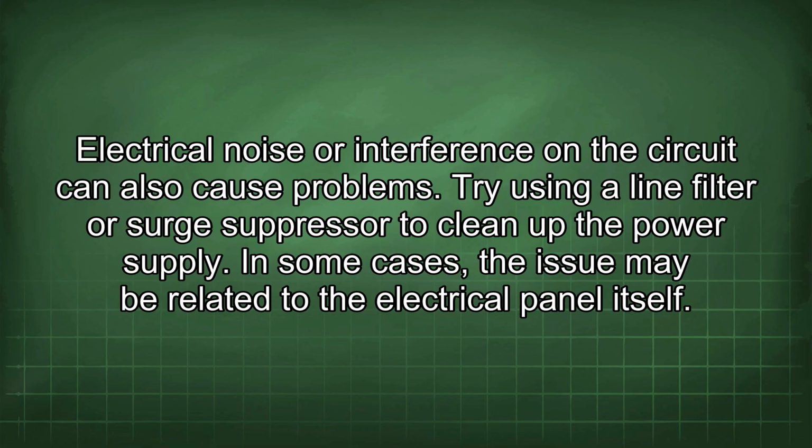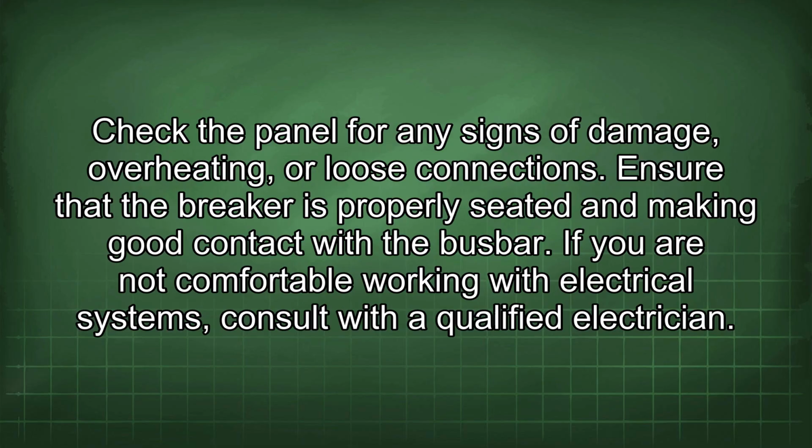In some cases, the issue may be related to the electrical panel itself. Check the panel for any signs of damage, overheating, or loose connections. Ensure that the breaker is properly seated and making good contact with the busbar.